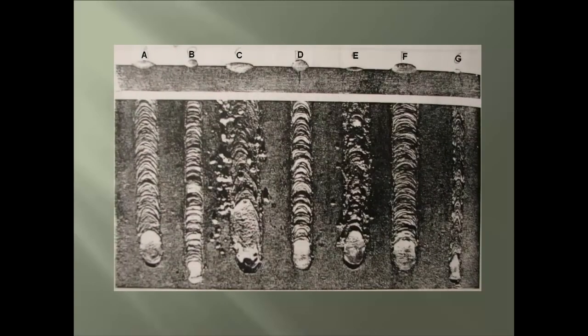And the last defects are the actual weld beads themselves that are affected by the weld current and techniques. So we see some major examples of weld beads. First, we see a proper weld bead which has the proper current and technique. Now we see a set of weld beads which show the current being too low then too high. Notice the difference between these two and the proper weld bead.